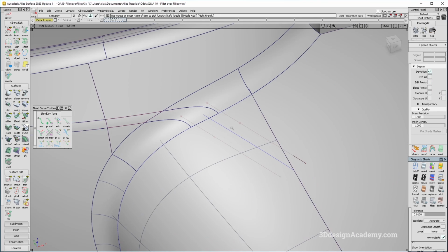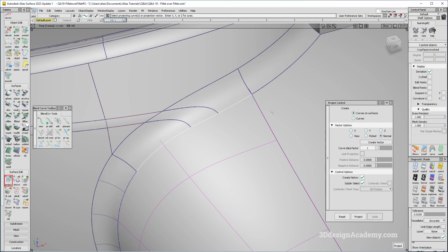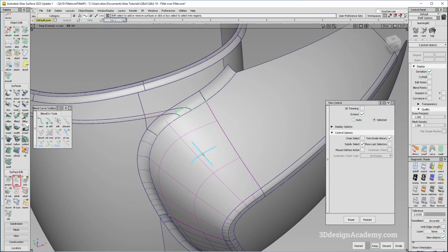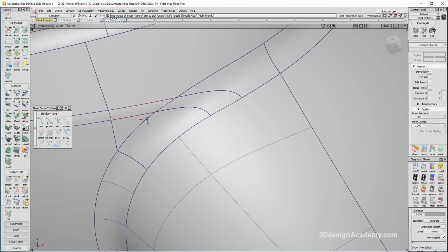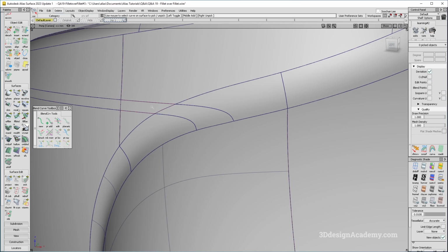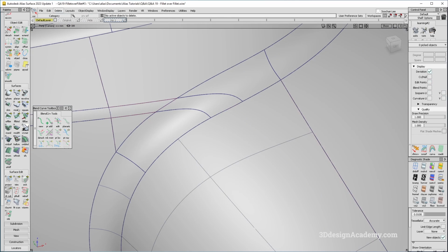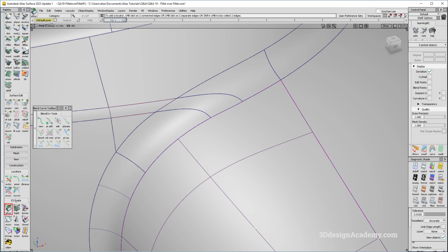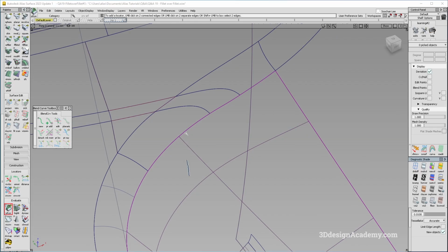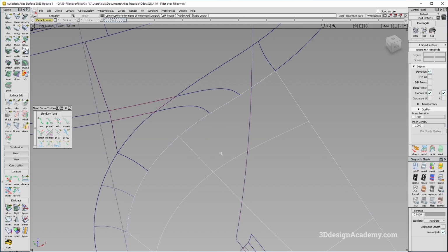All right, so the only thing I need to do is check the continuity on this side. Hopefully I don't have to do anything. I'm just going to project here, here, here. Now this one should be a little bit easier to fit just because it's just one surface and everything should line up nicely. So I'm going to go ahead and delete the construction history over here. Looks like there's some kind of COS there, but whatever. And I'm just going to, oh, yep, I already trimmed it. So let's check the continuity over here. I don't know what happened, but oh, there it is.